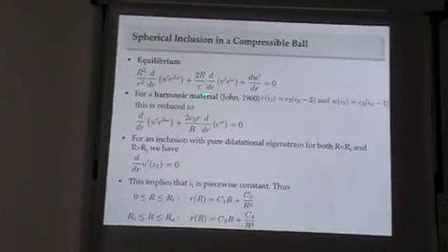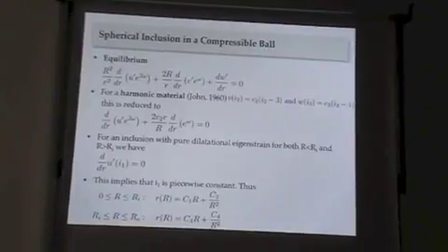So one is harmonic material, which means your V is linear in I2, linear in I3, but then the I1 dependence is an arbitrary function. And Carroll showed that it cannot be linear. If they're all linear, you would have zero shear modulus, or Poisson's ratio is -1. That's unacceptable. So when you take these two to be linear, the other one cannot be linear. And so you have this one governing differential equation, nonlinear, looks like this.